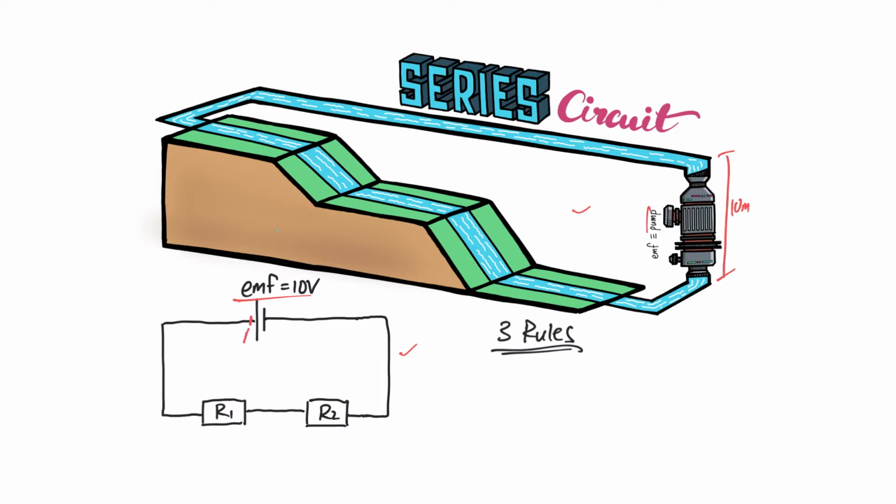And if I were to label this point here as A, and just before it enters R1, let it be B. So this part here is just copper wire and is represented by the point A here, and the section of the river where there's no change in height, that is your copper wire. This is point B, and then enters into R1. When the current flows into fixed resistor R1, there is a height drop in the system, in the river system. So this corresponds to your R1 and this corresponds to your R2.